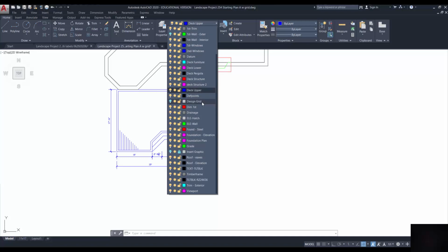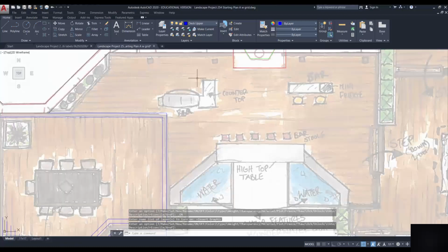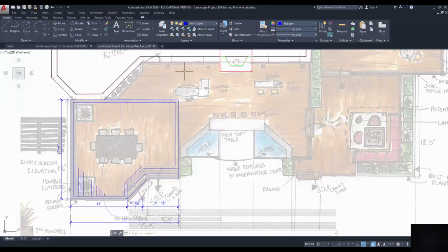Now, because they change the actual direction of the boards, it's actually going to change the direction of the framing. I got to be able to support the framing in one direction for the boards in that one, and in another direction for the boards in this one. So it's very critical that I understand where the different board directions are. So when we get to framing it, we can complete this project knowing exactly how the substructure is going to look.